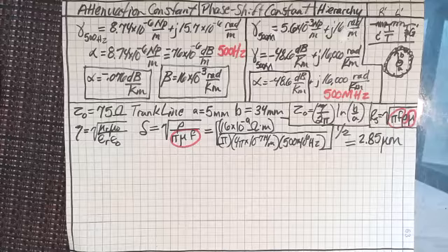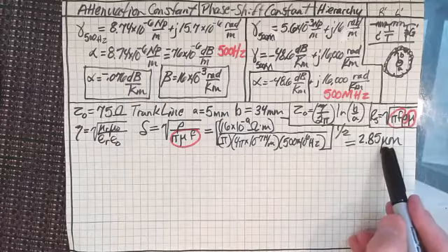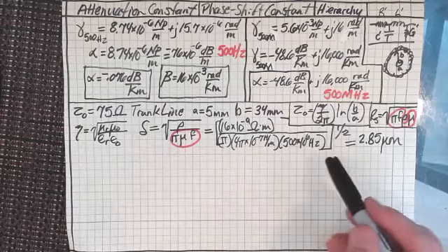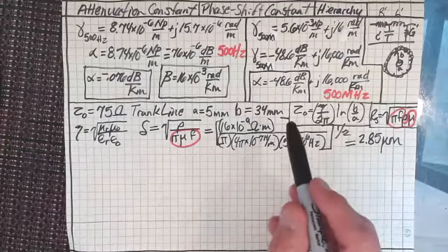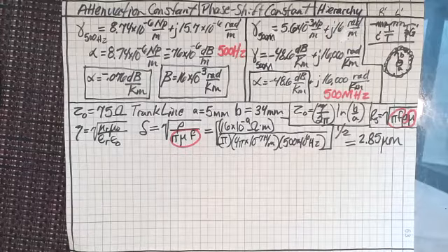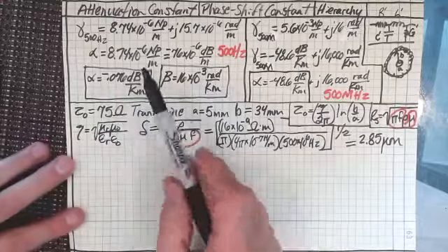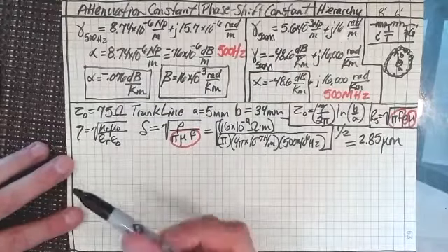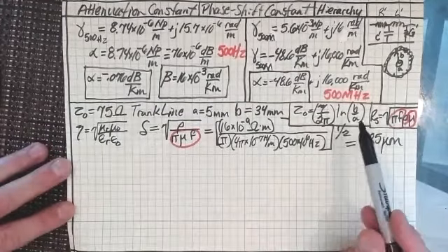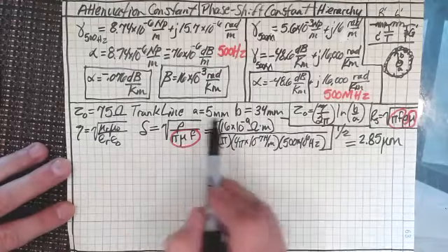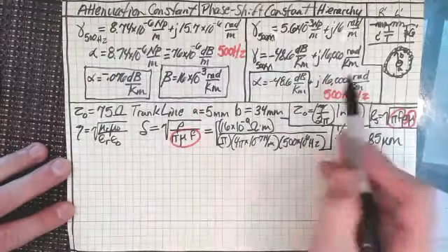However, let's go back now and analyze this. Now that we know how this feeds into the design of the trunk line coaxial cable, let's feed back into the things and see what we get. Well, we know that it's going to have the same ratio of A to B, right? So we know a couple things. And we know that this uses the same dielectric, right? So it's got the same dielectric in the trunk line as we have in the coaxial cable.